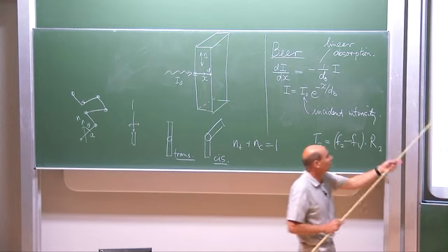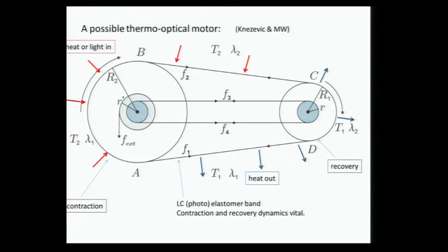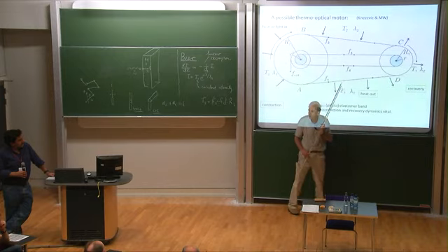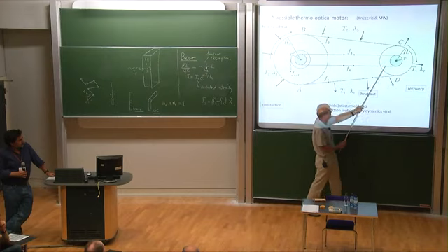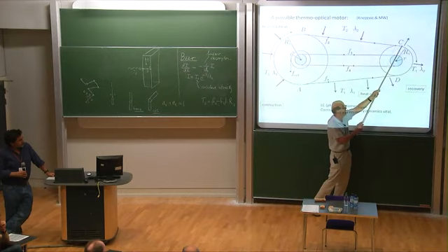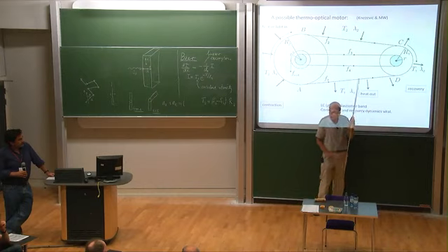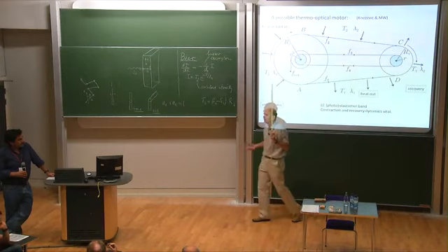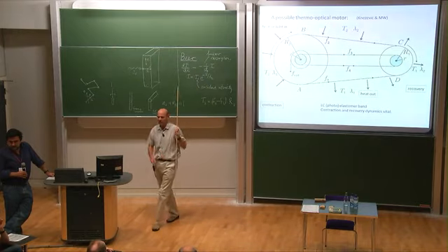So there's a net torque on this wheel this way. But that's not the end of the story. There's a net torque on this wheel, which is the other way. And you would worry about that because the two are rigidly connected with each other. But all that does is convey a torque from this one to this one, which is opposite and of magnitude F2R1 minus F1R1. And that's smaller because R1 is smaller than R2. And therefore it has to turn.